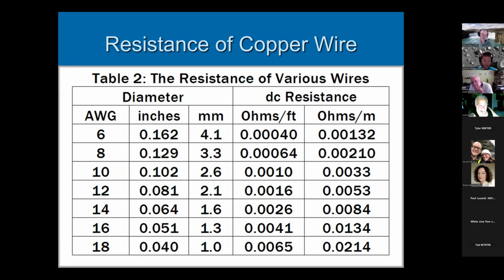There we have a lot of trade-offs between losses and throwing extra money at extra large conductors to minimize those losses. We can see that at 6 gauge wire, we don't have much loss. When we get up to 16 and 18 gauge wire that is a lot thinner, our losses start getting significant, especially if we're going any distance at all.